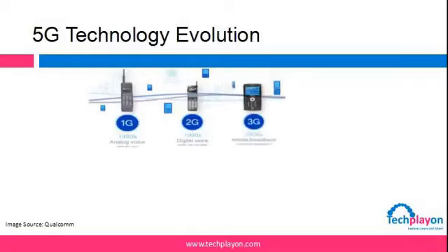The next generation of wireless communication was 3G with technologies like WCDMA, HSPA, EVDO, which are capable of providing both voice service as well as data services. 3G was able to provide somewhere around 10 Mbps of data rates. Next we got 4G technology like LTE, LTE Advanced and WiMAX, which can provide data rates of 100 Mbps, LAN cable connected type capacity over the wireless link. 4G introduced the concepts of orthogonal frequency division multiple access and MIMO to achieve this high data rate.